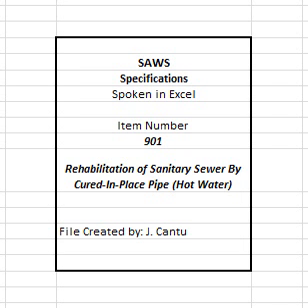C. The layers of the cured CIPP shall be uniformly bonded. It shall not be possible to separate any two layers with a probe or point of a knife blade so that the layers separate cleanly or the probe or knife blade moves freely between the layers. If separation of the layers occurs during testing of field samples, new samples will be cut from the work. Any reoccurrence may cause rejection of the work. D. The CIPP shall be classified as conforming to the following structural properties. E.